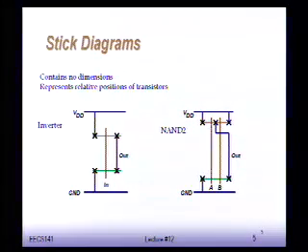A stick diagram is a representation of the relative positions of the transistors in a standard cell, in a digital gate, basically. It doesn't have any size information associated with it. All it tells you is just the relative position of the transistors.